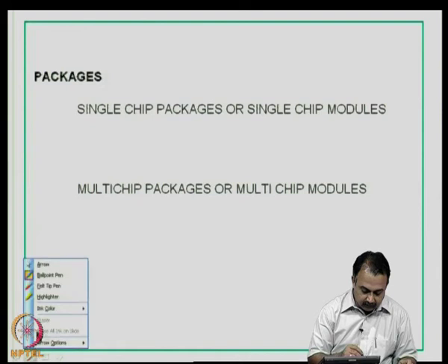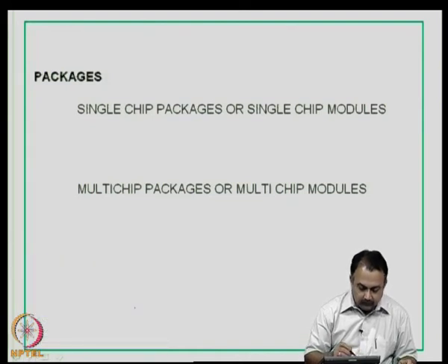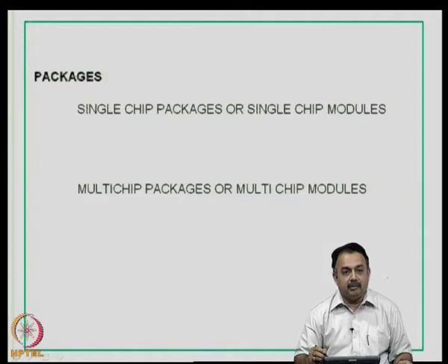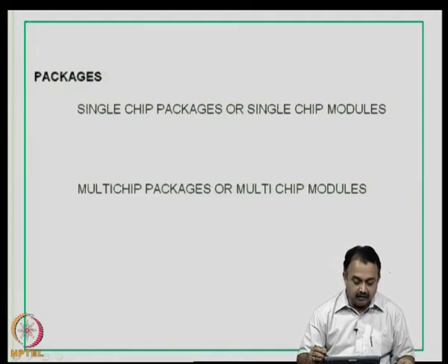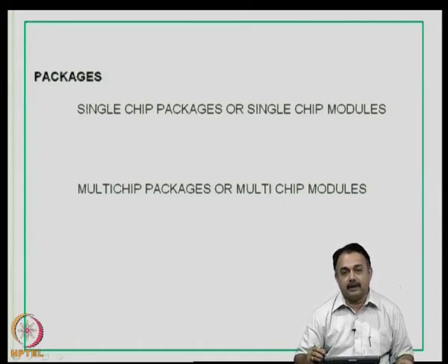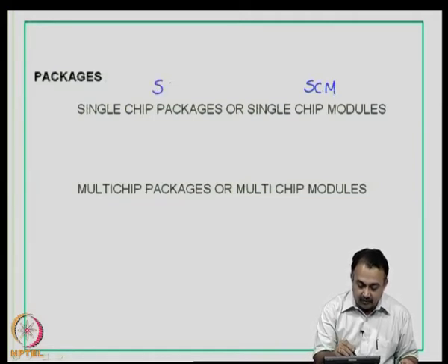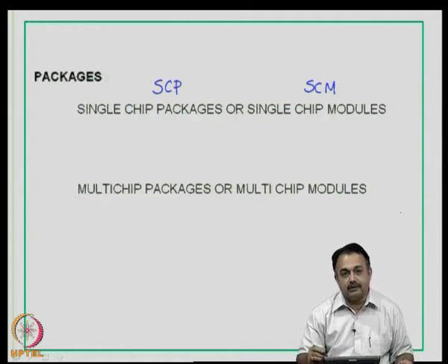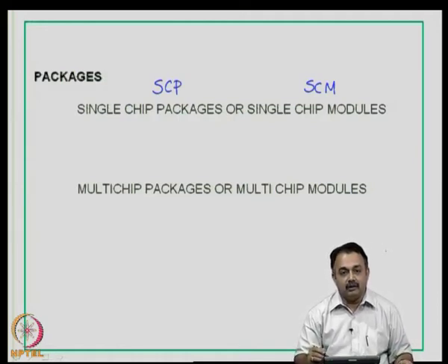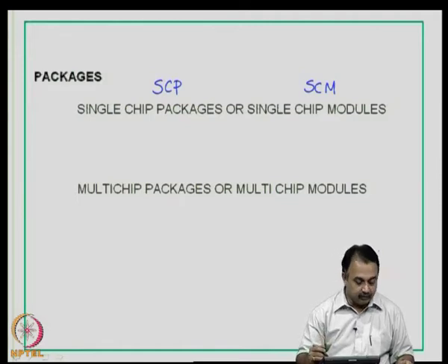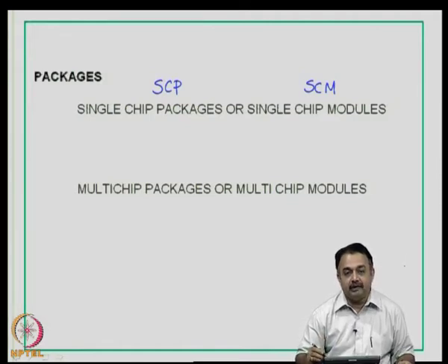So, we will now look at the packages. What do you mean by packages? Broadly, we can define packages as single chip package or single chip packages, or another term used today is single chip modules. You call it as SCM. Sometimes this acronym called SCP is used. So, whenever you look at this acronym in the packaging context, you can identify them as single chip packages or single chip modules.